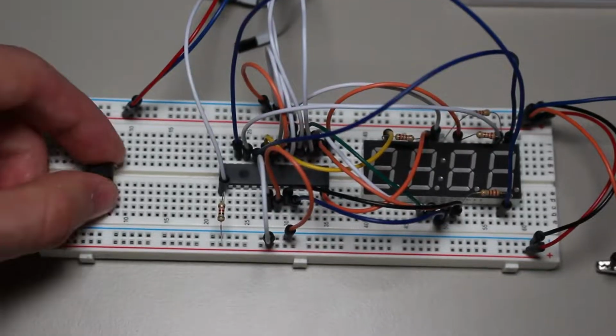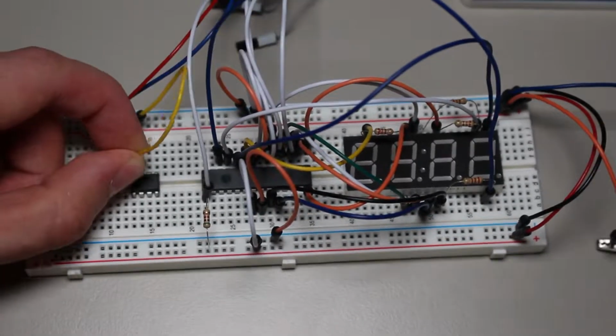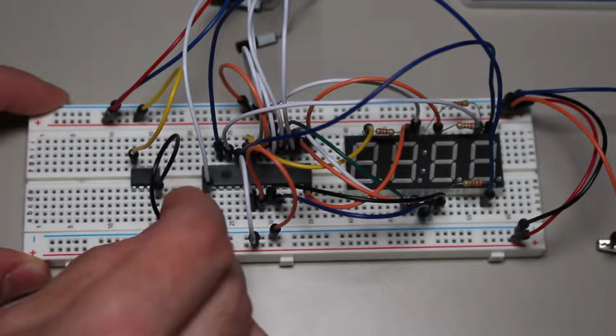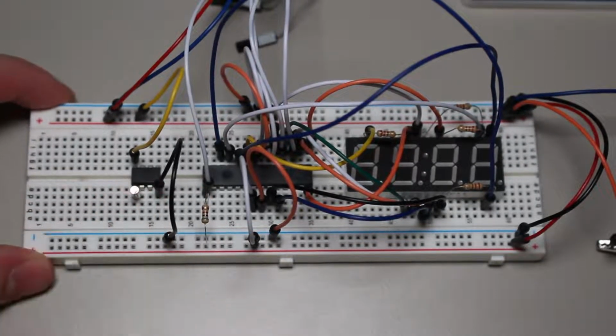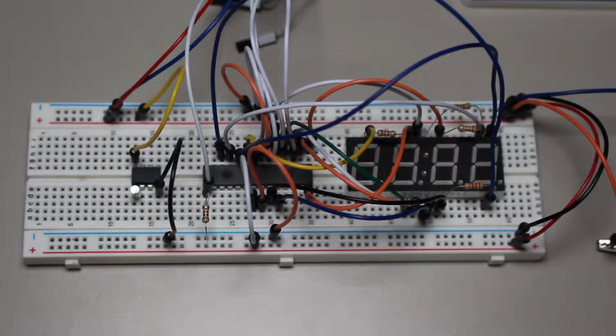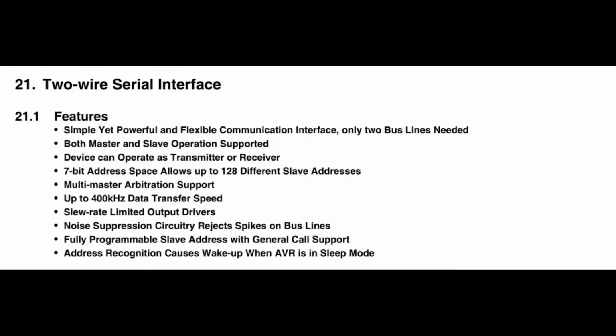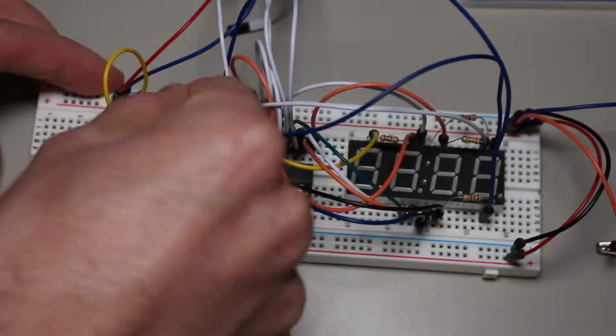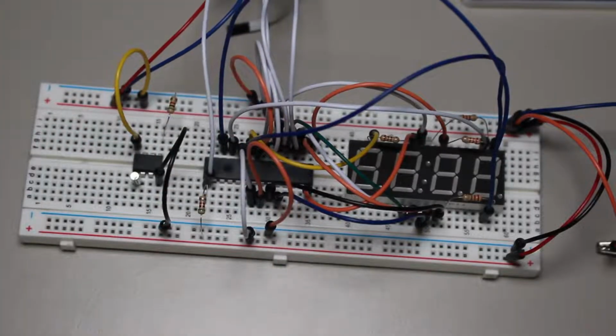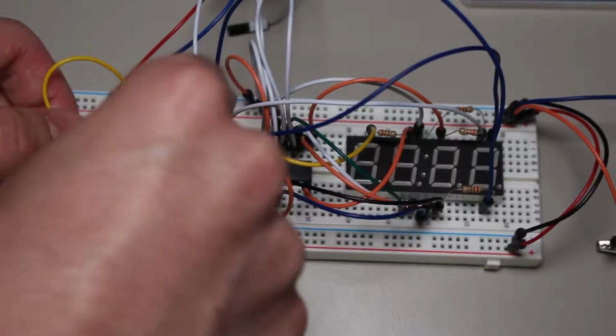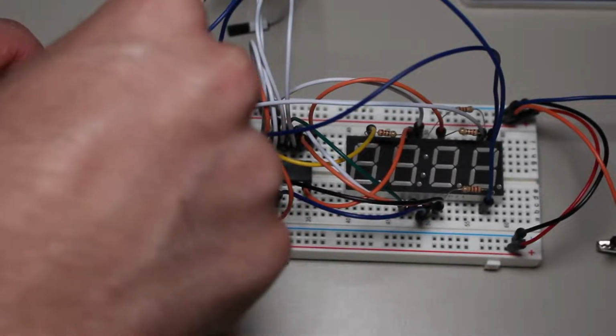After setting up the display, I wired up the DS1307 with a 32.768 kHz crystal to my microcontroller. Luckily, the ATmega already comes with hardware I2C support, although they call it TWI, or two-wire interface, in the datasheet. So we can connect the SDA and SCL pins directly to each other. Also, don't forget to add the pull-up resistors to these pins because they are all open drain.